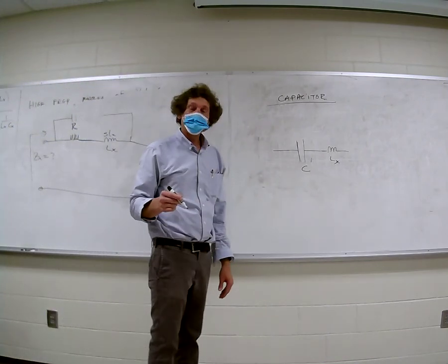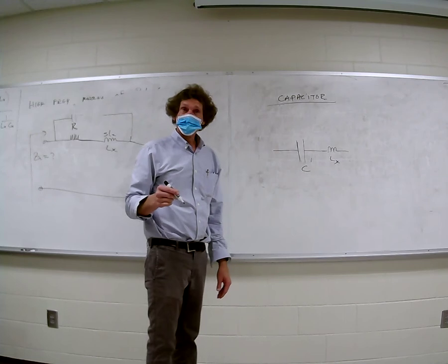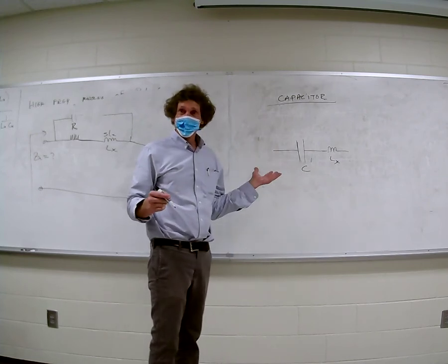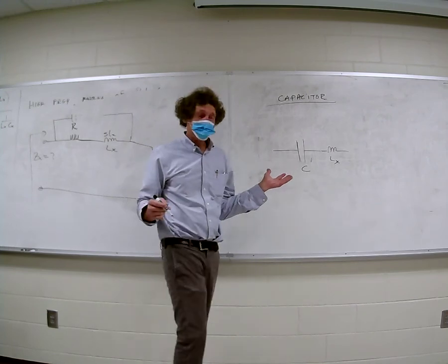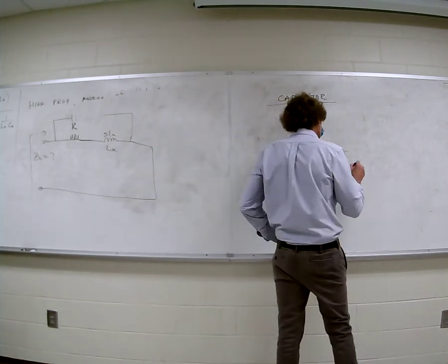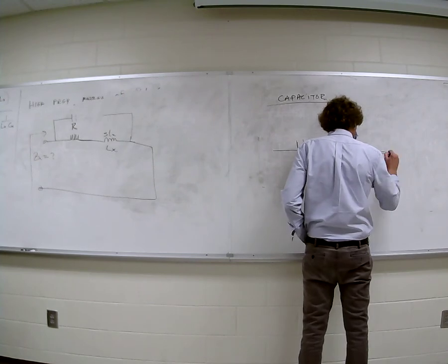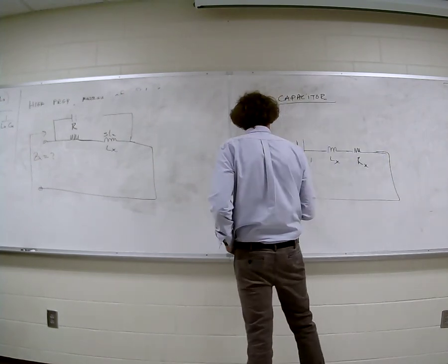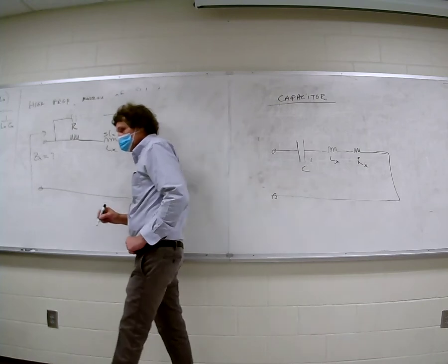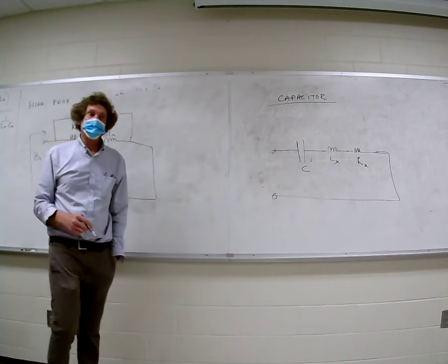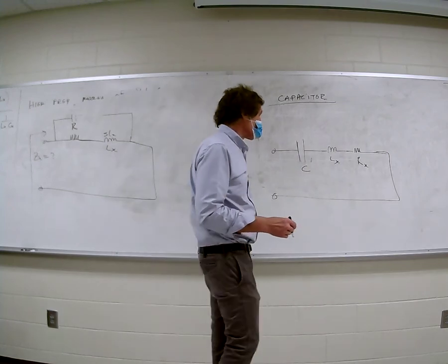Now, unlike the other ones, there is no parasitic capacitance for the capacitor. It is the dominant capacitance. You don't have to worry about it. But there is some resistance, because anytime you have wire, you have resistance. And that's the model. Three elements in series is what it looks like. You with me? Now when you look at that, you got R, L, and C.